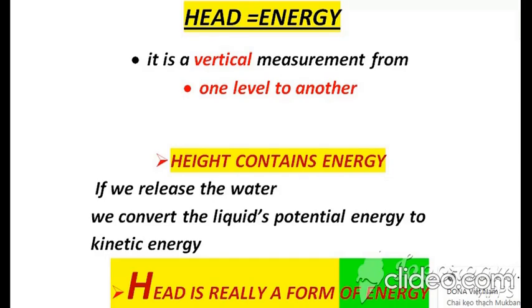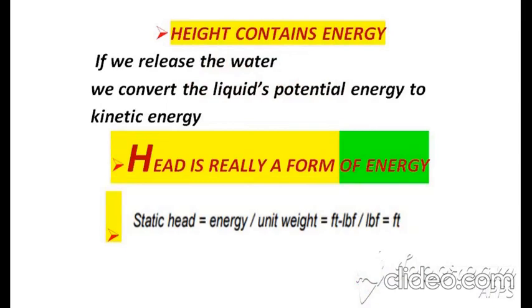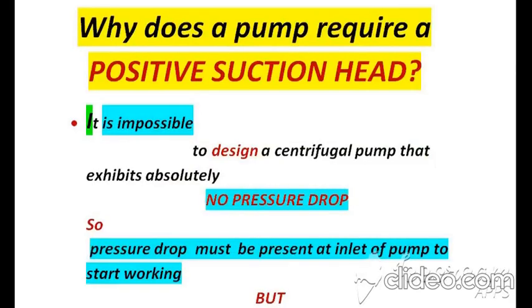So it's proved that head is equal to energy. The conclusion is that head is really a form of energy. According to units, here we are using energy units, and the result is still feet, which is a height and also a head. After getting a lot of information about the word head, now we are running towards our main topic, which is net positive suction head.